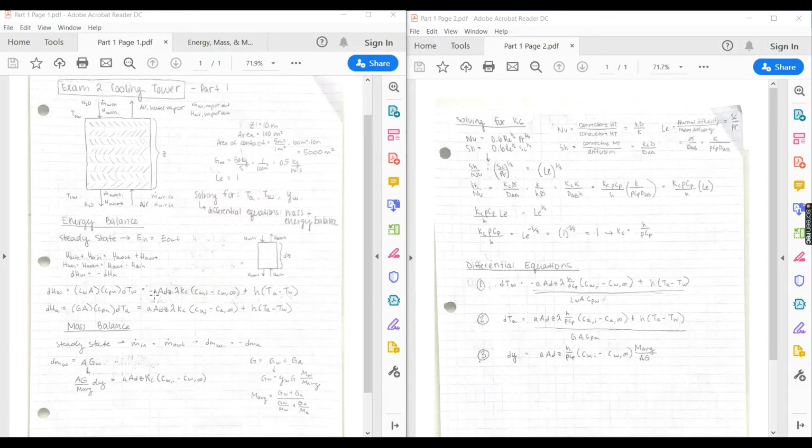So we have this small a, which refers to the area per volume of the system through which the water can flow, times the area times the length, so times the volume. This first part of the equation gives the contact area through this control volume. We can then multiply by the heat of vaporization, lambda, which would be written in terms of joules per mole, and then we would multiply by the molar flux of the water, so that this section right here would be in terms of joules.